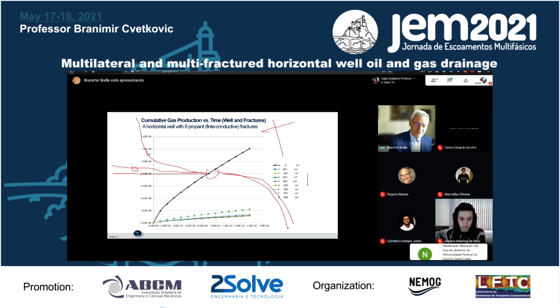Final comments. Study results may be used for better estimation and understanding of fractured wells. Obtained results have to be verified, okay? And of course, we need to introduce PLT data. PLT data will be data when you have a well and you produce from these fractures. Up to now, I modeled it, but they really measure these rates. You see?